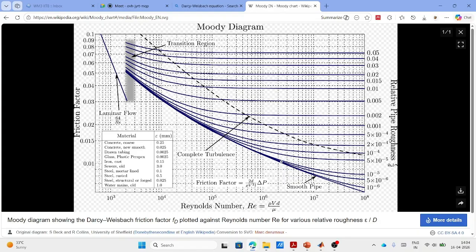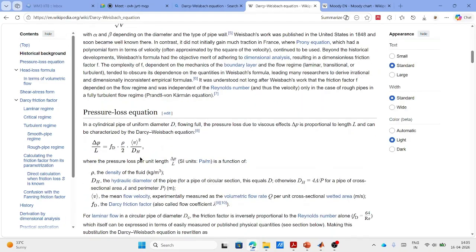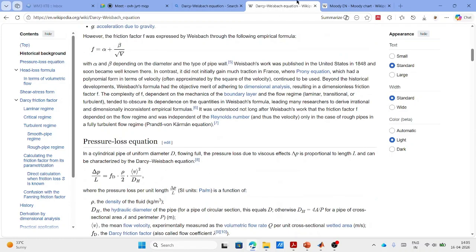Now, ideally, when you are computing it, to understand what the friction factor inside this pipe is, you will first find the Reynolds number, and corresponding to that Reynolds number, find what friction factor you have. You find that friction factor and you put it into your Darcy-Weisbach equation, right? Here to find the total head loss that is occurring in your system.